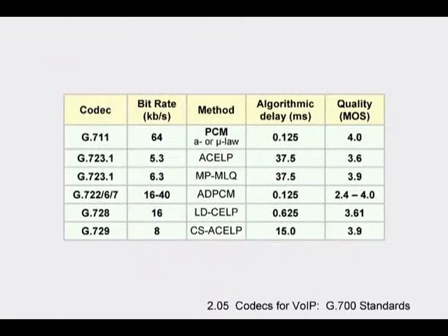Most of the other techniques are based on something called linear predictive coding, LPC. And this is based on building a mathematical model of what somebody's throat looks like, and then predicting what is going to come out next based on what came out recently. And I'm talking on a millisecond by millisecond basis here. And the idea is, if you get a real good model of the throat, then your prediction of what's going to come out next based on what came out recently is going to be quite good.